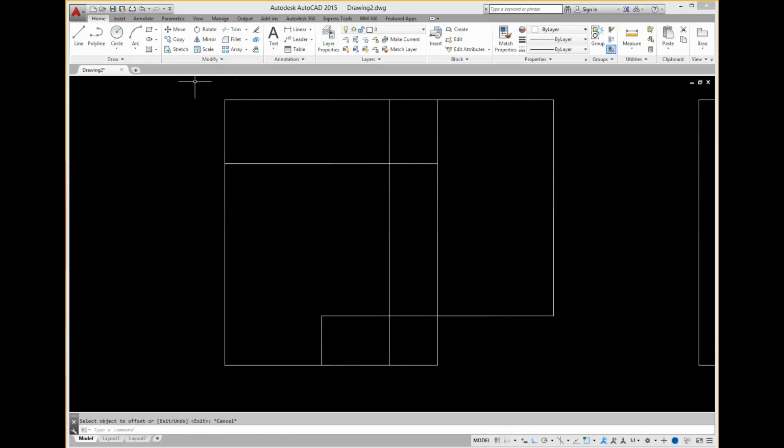Click on the trim button here and enter right away. You have to enter immediately for trim to work this way. And we are going to trim out some lines here, here, and here. Now we're going to create some wall thicknesses. The walls are 3 1/2 inch thick. They call them 4-inch walls, but the framing lumber is 3 1/2 inches.